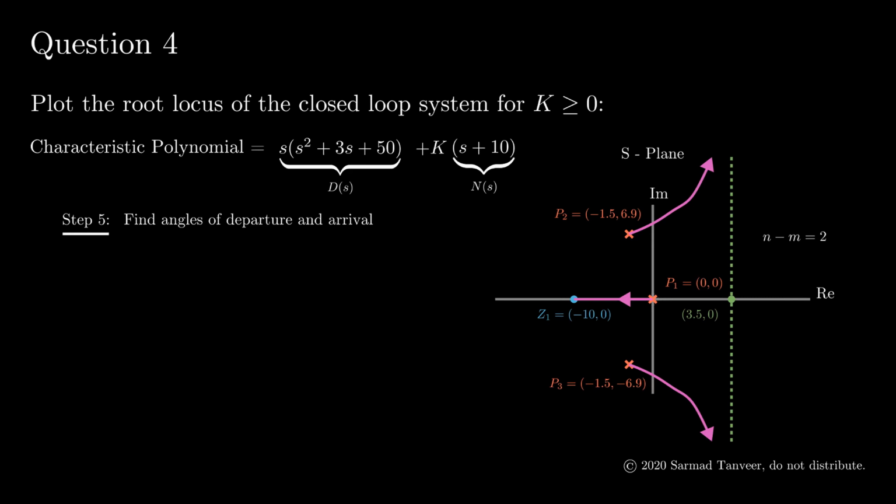Something to mention here is that we did not create the root locus where the range of k is less than or equal to 0. This is commonly referred to as the complementary root locus of the system. I wanted to highlight that while the process of drawing the complementary root locus is very similar to the process we just followed, the rules and formulas used can actually differ, so make sure to use the right type of formulas and rules for each root locus plot.